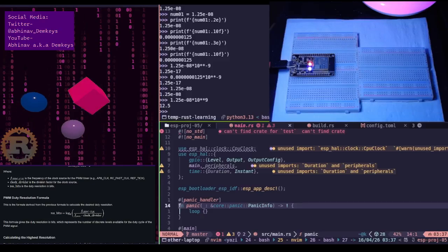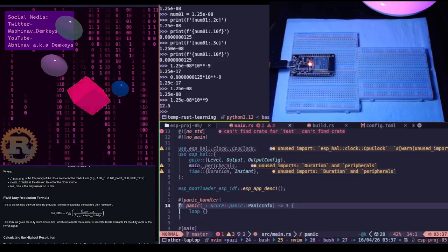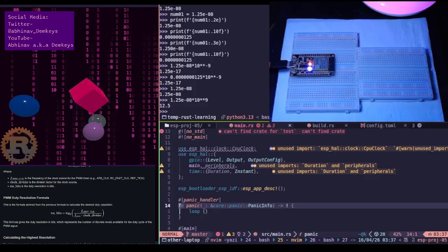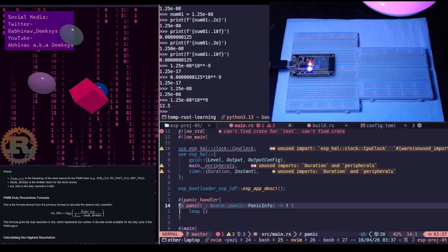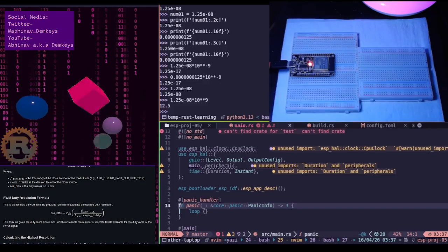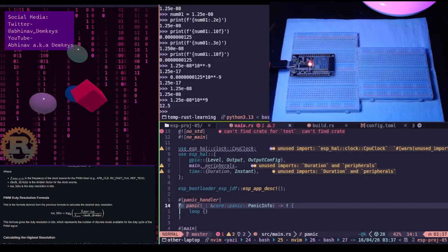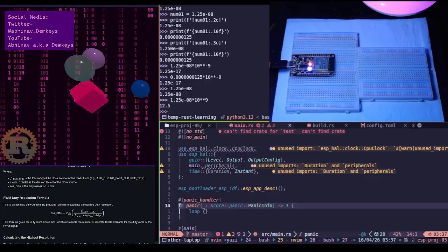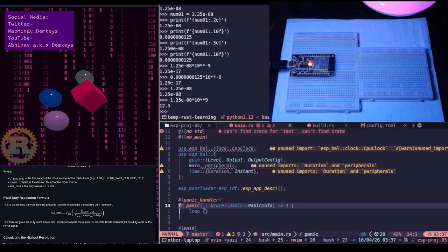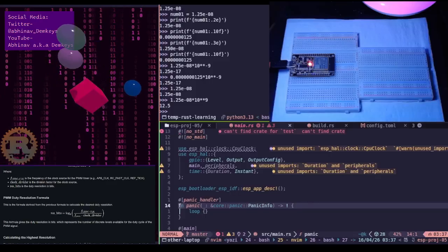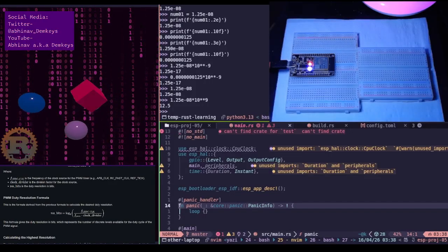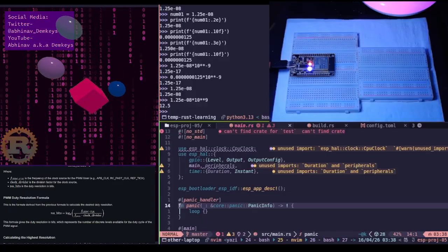And if I want to connect both of them together, I need to take into account certain things about how both these circuits work, because while the ESP32 might not cause any sort of interference, it turns out the ultrasonic atomizer module apparently creates electromagnetic interference, and that can come back through the ground line to the ESP32 and disturb its working.